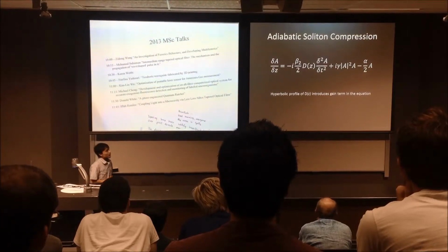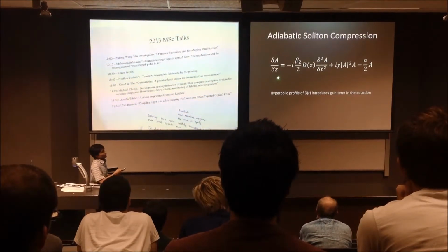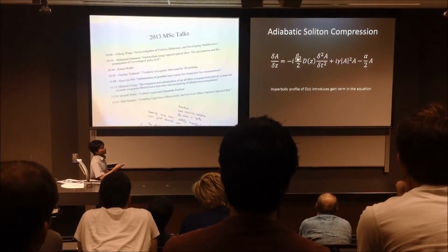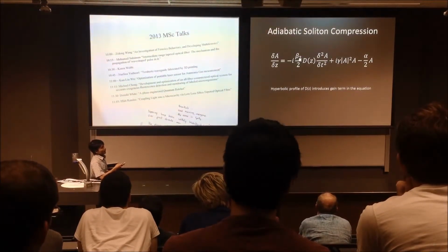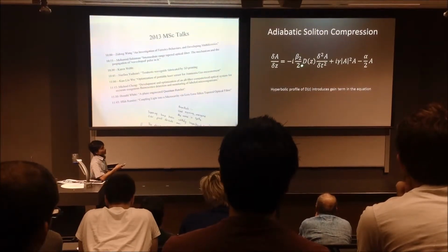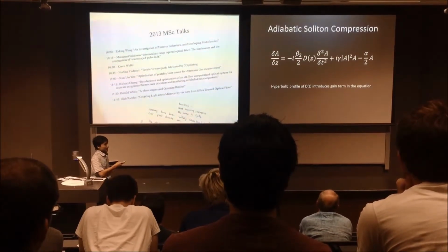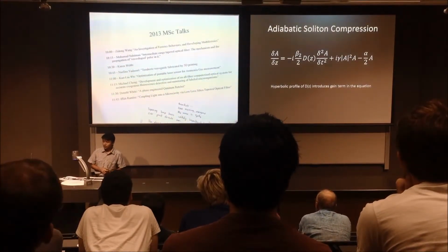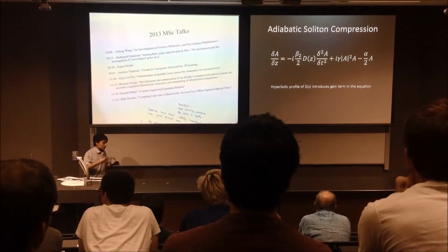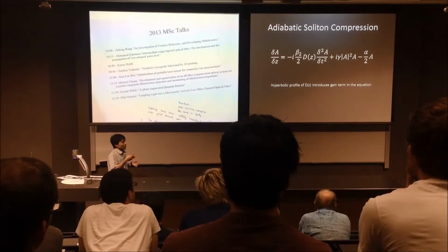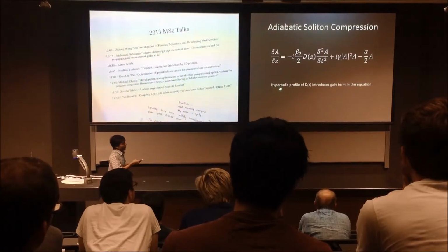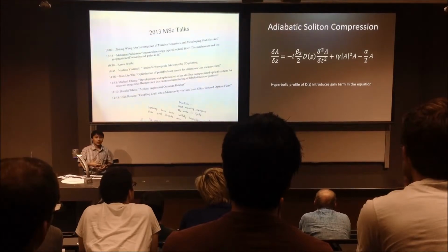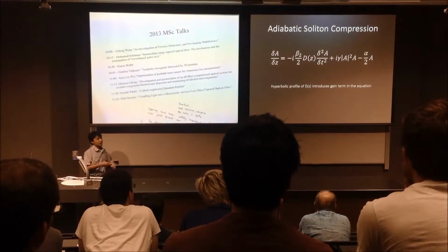For simulation of soliton in a fiber, we use a nonlinear Schrodinger equation. We alter it a little bit because we have beta 2 changes in spatial space. So we have dz from 0 to 1 as a decreasing function. And by specifying this dz and having a hyperbolic profile, this change in beta 2 will result in a gain as the pulse propagates down the fiber.